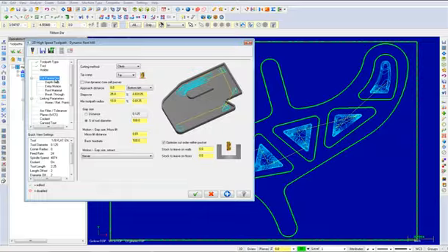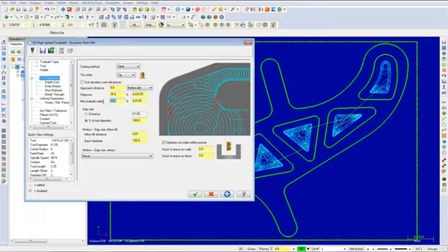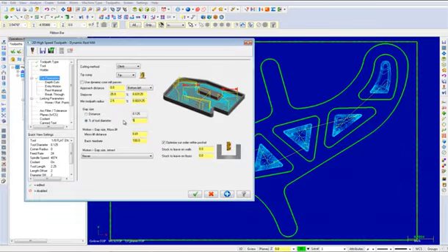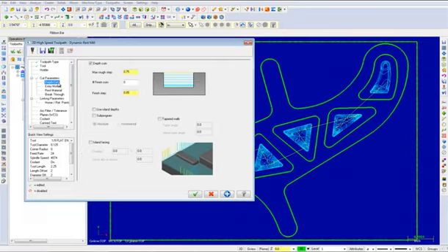Make sure that the parameters are matching. Make the following changes as shown. Once complete, select the depth cuts. Change the max rough step to a value of 0.375. From here, select Rest Material.